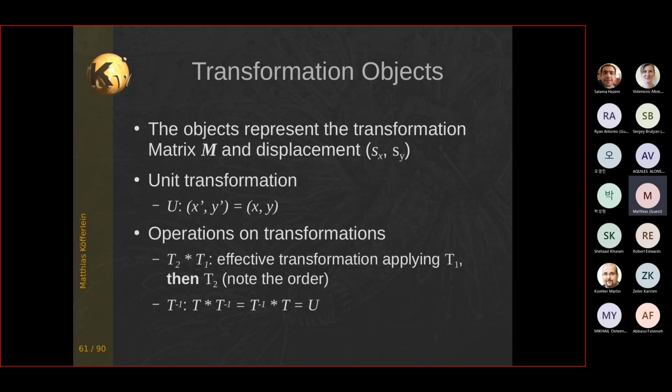Bottom line of that is a transformation. Instead of saying I shift a box, for example, or I shift a polygon, or I rotate a box in the sense of a method, I can define a transformation and apply this transformation to the box or to the polygon. And the advantage of thinking that way is that transformations are universal concepts, and I can compute transformations. And transformations play an important role in building hierarchies, because when I place a cell, this is basically a transformation of the content of the cell. So a cell can be placed, which means I shift everything inside a cell, but it can also involve rotations, mirroring, and so on. So a cell placement is eventually the specification of a transformation.